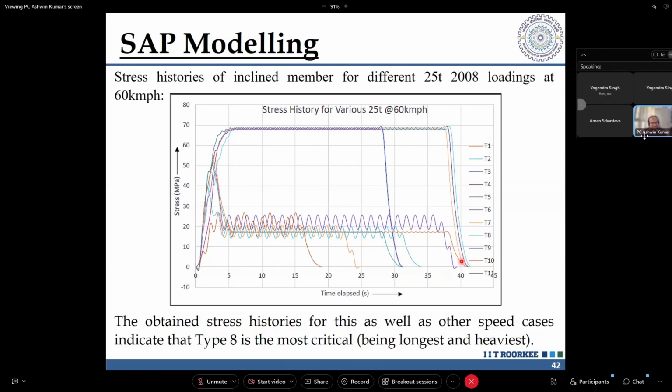But what is interesting to see here is that there is a cutoff limit for fatigue, which is applicable for both constant amplitude loading as well as variable amplitude loading. But the fatigue limit at 5 million cycles presented here is only for constant amplitude loading. That is all fine, but when the bridge is run over by a vehicle, the loading is not constant amplitude. It is variable. It has variations in its loading cycles, right?